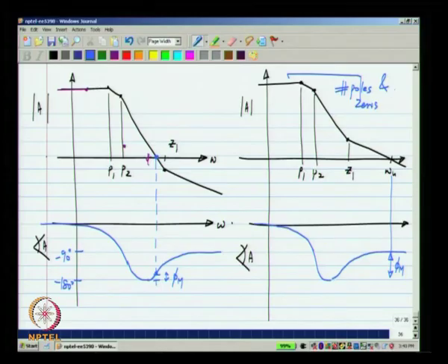So, in fact, the number of poles and zeros before the unity gain frequency should be such that the number of poles minus number of zeros is 1. Earlier we had articulated the stability criterion differently. In fact, we were only looking at cases where there was a single pole before the unity gain frequency or unity loop gain frequency to be precise, and we could have more poles beyond the unity loop gain frequency, and we said that they should be sufficiently far beyond the unity loop gain frequency. Now, that was a restrictive case.